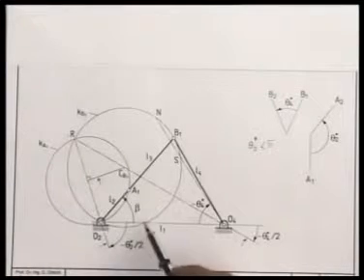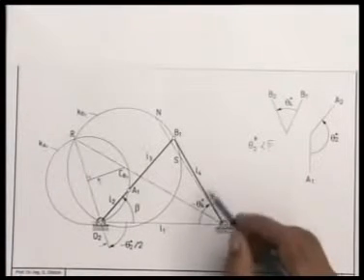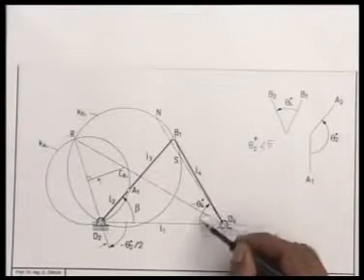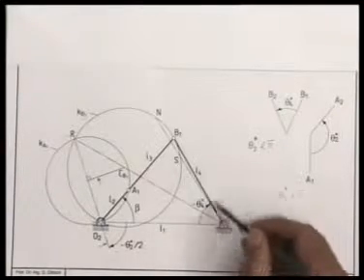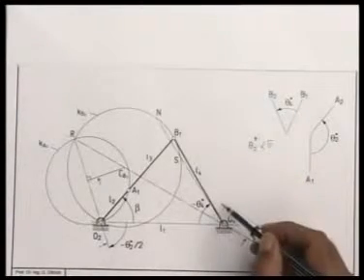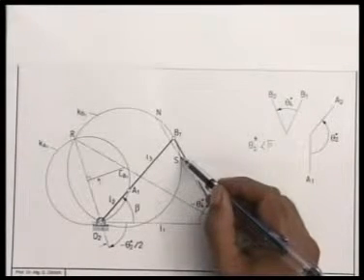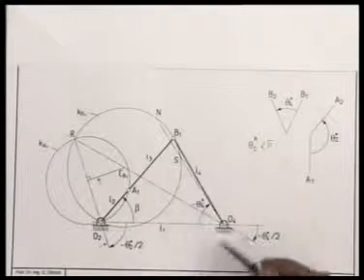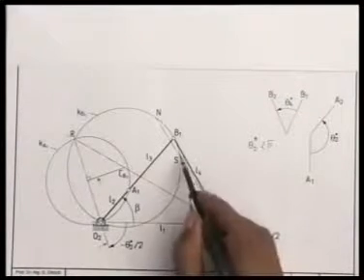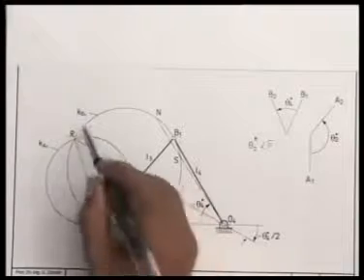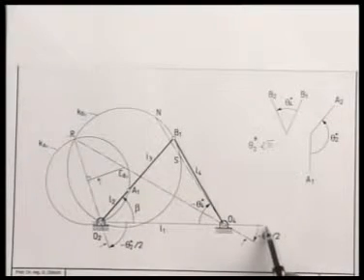But now, if I draw the line O4N at an angle minus theta 4 star, then that line O4N comes out like this, intersecting KB1 here again at S. Previously this point of intersection was below O2 O4, and I considered S the intersection of KB1 with O2 O4.